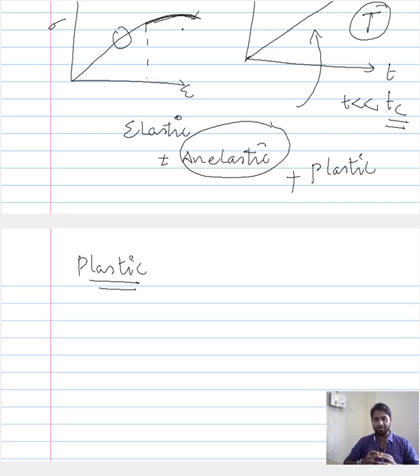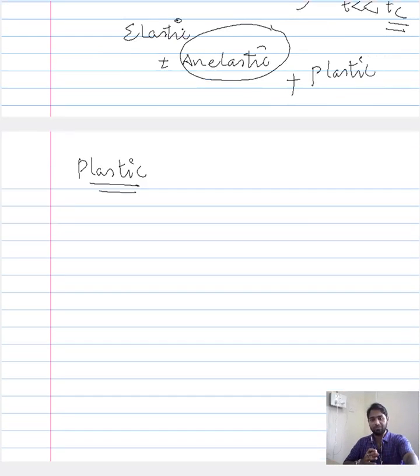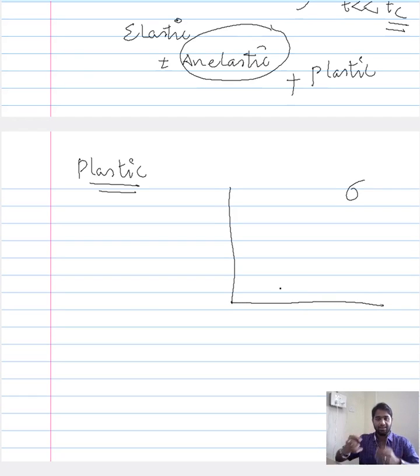In our case, we have already imposed a condition that we work under the criteria that the mechanical condition that we impose will not change. So the mechanical condition that we impose is going to stay the same. In response to that condition, for the dislocation to move, they need additional stress. However, we are under the condition that the stress that we have imposed is constant. So in combination of these two, what happens is that the strain exhibited by the material decreases with respect to time. So let me repeat.